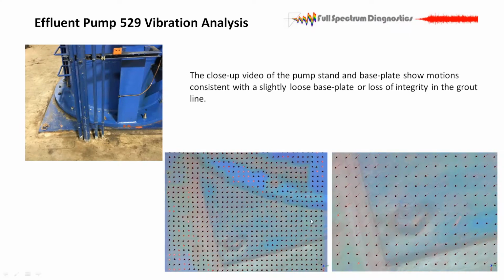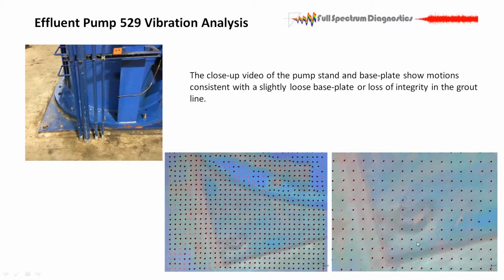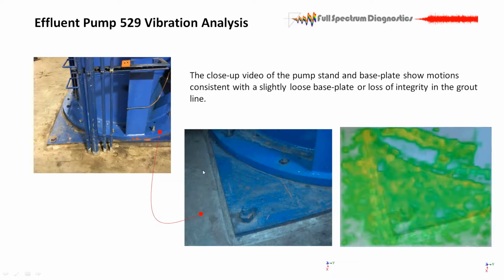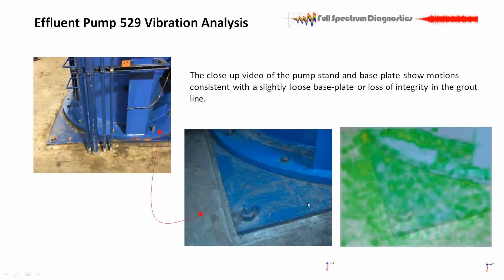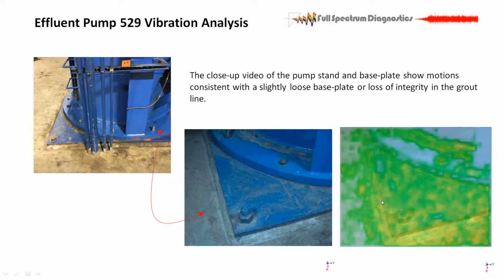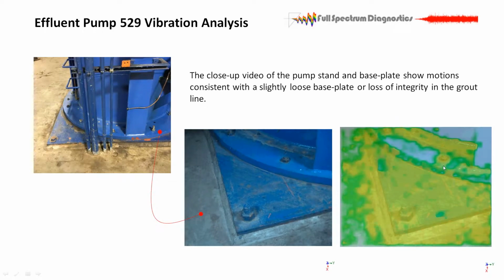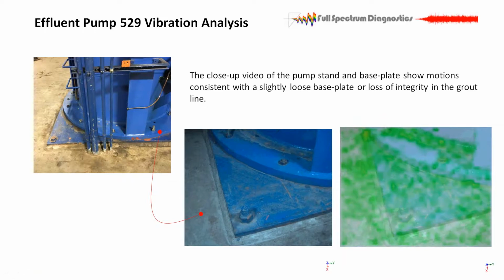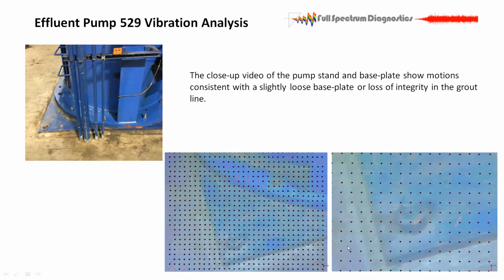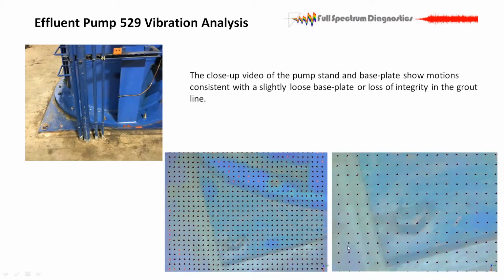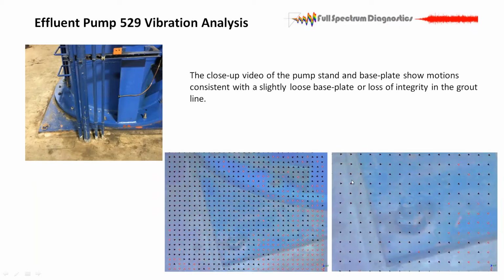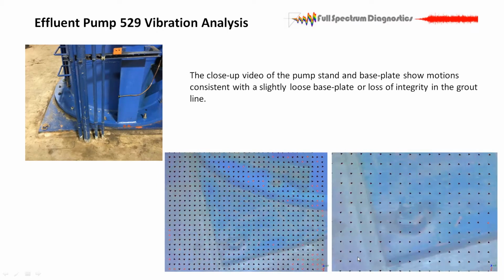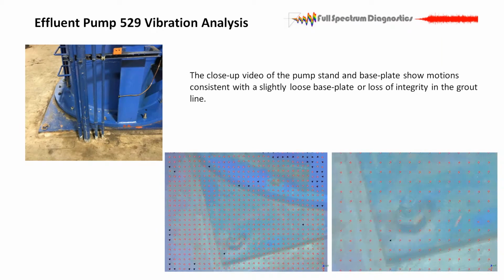Okay. Another feature, it's not something that you'd probably want to leave on, but just like this, it's hard to look at something like this and see little minute details. It's a lot easier to see when you have the color contour where all the motion tends to be, and then it does help a little bit to see how the vectors are flowing. And you'll see right away if something across this grout line is moving in the opposite direction, that would indicate a broken grout line. This is just small motion in the substructure.